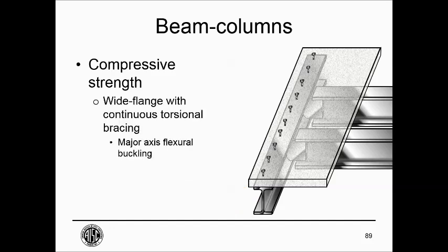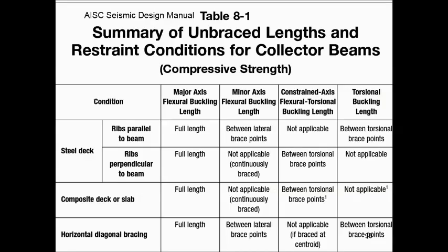So for the compressive strength, if you really want to squeeze every ounce of strength out of this, you can calculate the torsional restraint that's provided by the deck and consider also the flexibility of the web, but that's a fairly involved calculation and maybe doesn't get you that much extra strength. But our conservative methods are to design as follows.